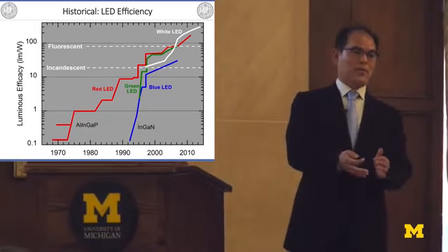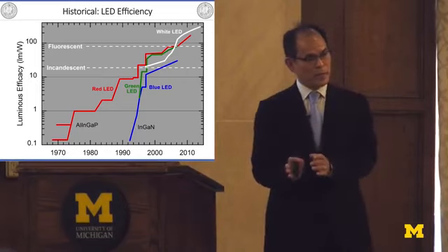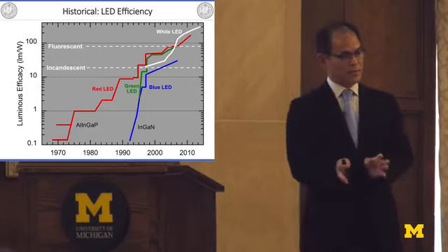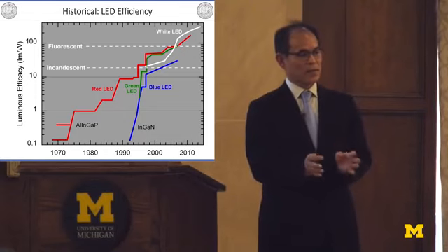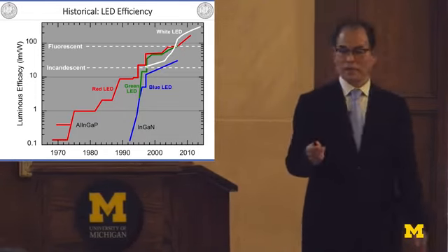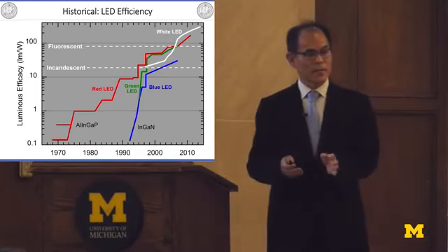The excuse was that for blue LEDs, I have to use MBE or MOCVD for crystal growth. I selected MOCVD because I saw it is much better for manufacturing. That's the reason I went to the University of Florida for 1 year.